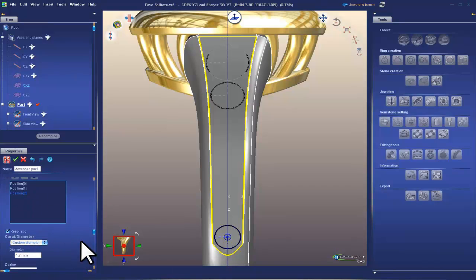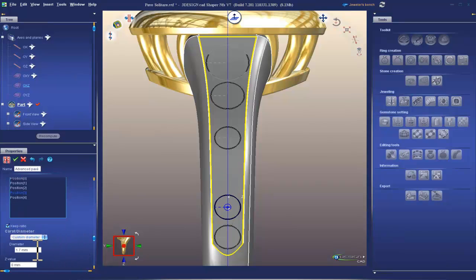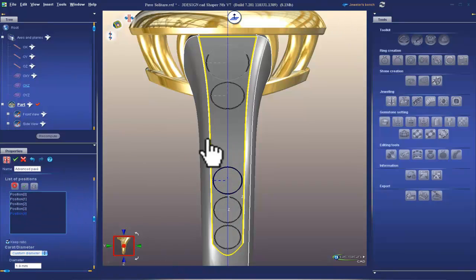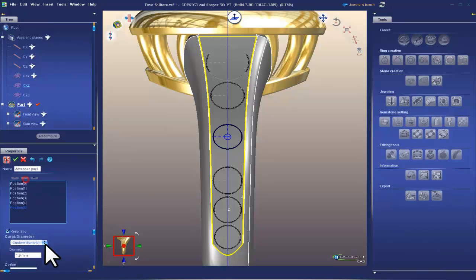And the reason I'm going up from both sides is I want to make sure that I end properly here and end properly at the top, so I can adjust the spaces in between. I have the minimum set at 0.2, but that doesn't mean that I can't go a bit bigger. So add a couple more stones in, bring it down to there. We'll make this 1.8. That was good. Like that. This one can probably be 1.9. That's good too. Add another stone. This one could probably be, we'll check it and turn that one to 2. Bring it down and